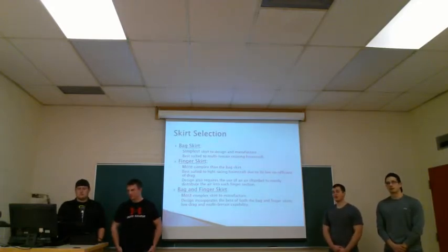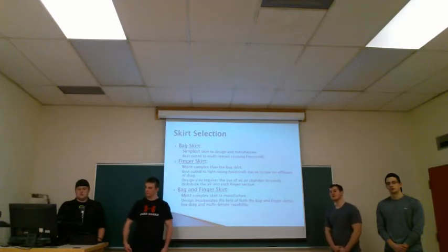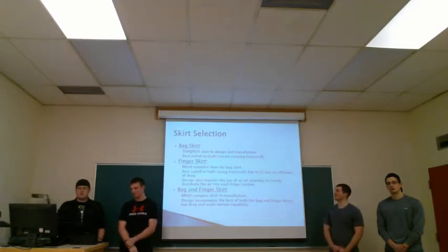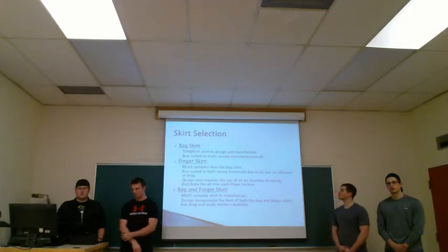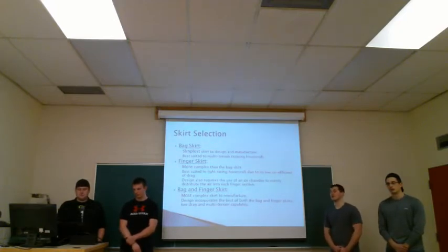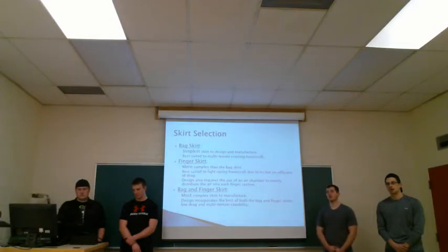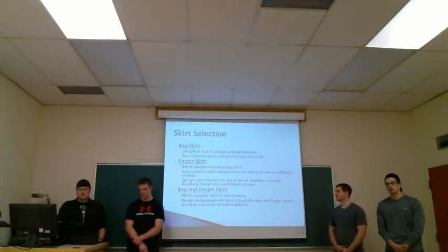Our finger skirt is a little more complex. It will take a lot more time to design and build a finger skirt. The finger skirt is best suited for light racing hovercrafts because it has low coefficient of drag. And design also requires the use of an air chamber to evenly distribute air into each finger of the skirt. And bag and finger skirt, this one is a more complex skirt. And design incorporates the best of both the bag and finger skirts, so it would end up with low drag and multi-terrain capability.